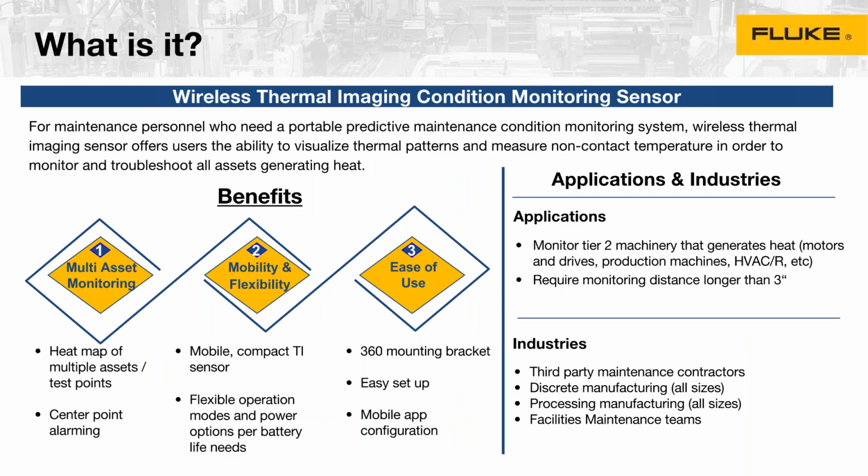And so some of the benefits you would have with a wireless thermal imager sensor kind of speak for themselves. First of all, if you put a sensor and leave it there, and it's far away in a room or you have enough room to monitor, you can actually monitor multiple assets. You can look at two motors at the same time, two pumps. You can do center point on one or the other, or you can simply have a reference in the background.